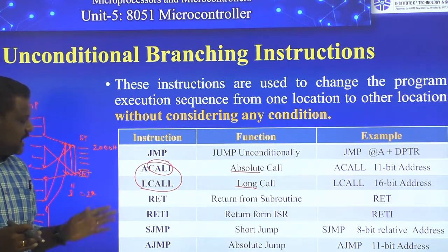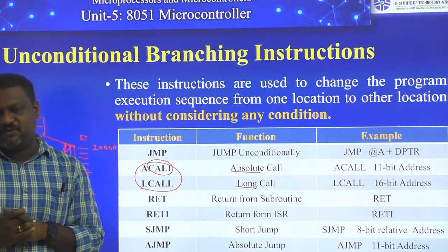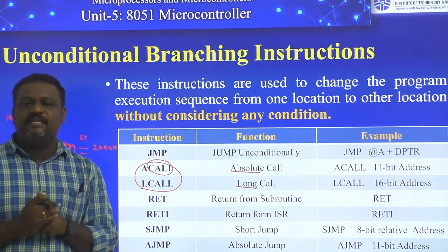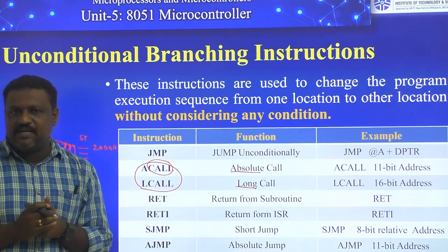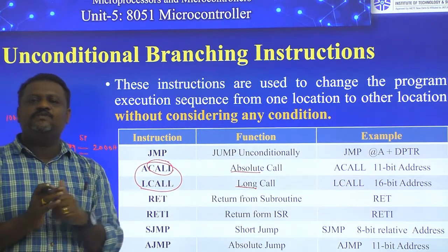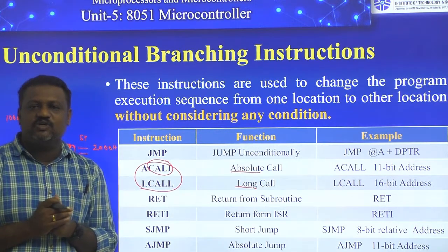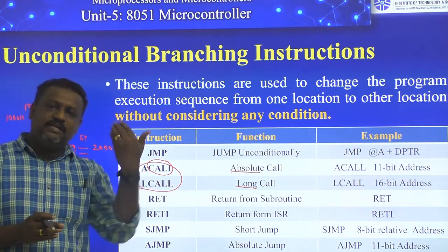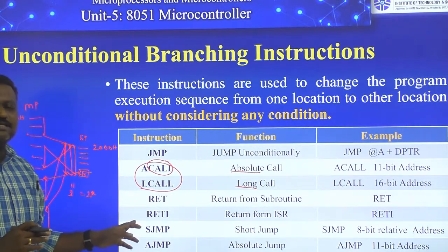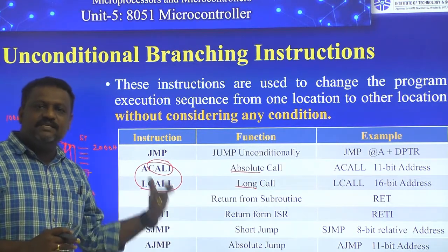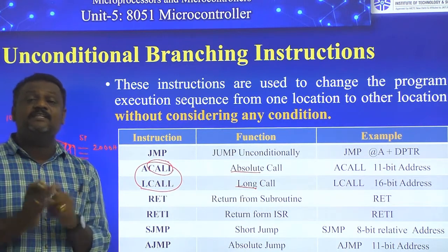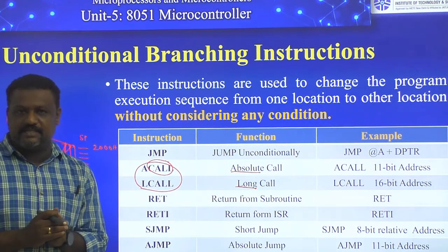Coming to one more variant, RETI, which means return from interrupt service routine. We know that your controller supports different interrupts, and when your controller accepts an interrupt from a device, it will provide servicing for it. In that process, your controller goes and executes a program called the interrupt service routine. Once it successfully executes that interrupt service routine, it will come back to the previously stopped program. To return to that program, the interrupt service routine must have a return instruction. That return instruction here is RETI. That means this RETI, which is nothing but return from interrupt service routine, is used as the terminating instruction for every interrupt service routine, ISR. So that is about this.